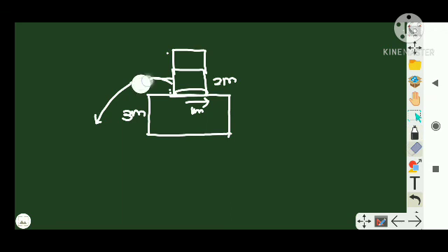Even if the figure doesn't look like a bottom, like this, right? So he asks what is the velocity by which it is coming out. This is something you have learned in the application of Bernoulli's theorem, right? When the water comes out like this from an orifice, it is just like a freely falling body from a height from the surface. If an object falls from this surface, what will be the velocity? It will be root of 2gh.